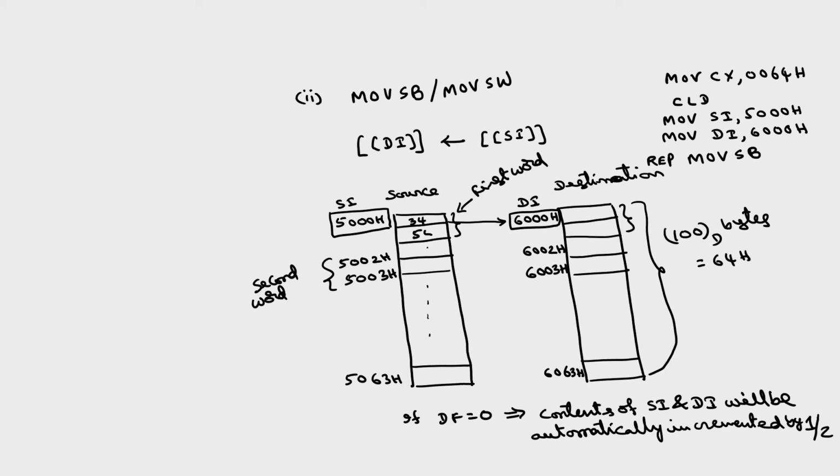Here, whatever data is present, suppose you have some 34 54, 99 AA, and this will be having CC 1D, 13 5A 6F. So, this instruction first compares 34 and CC. So, 34 minus CC will be performed, and because 34 is less than CC, the carry flag will be set.